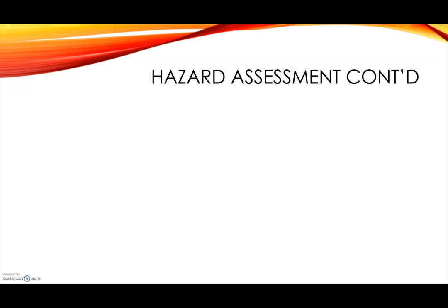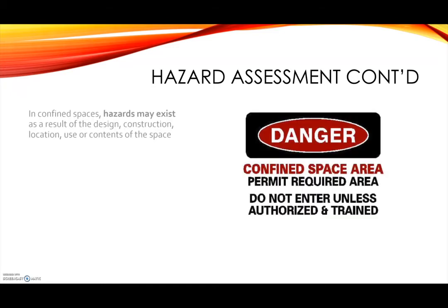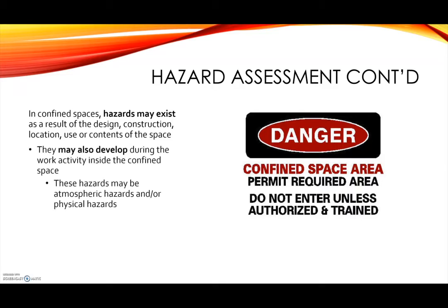Hazard assessment continued. In confined spaces, hazards may exist as a result of the design, construction, location, or use of the contents of the space. They may also develop during the work activity inside the confined space. These hazards may be atmospheric hazards and/or physical hazards.